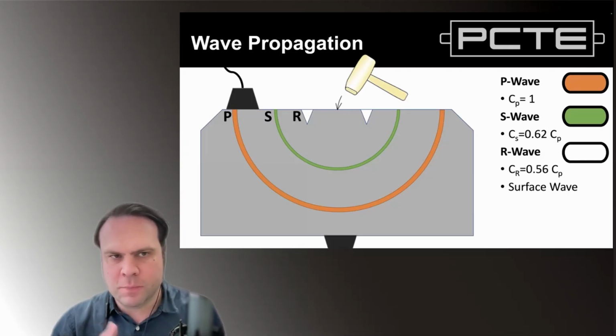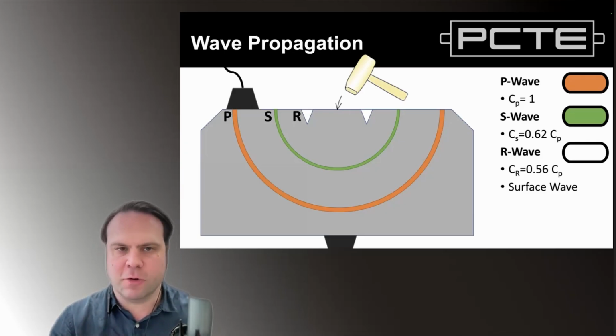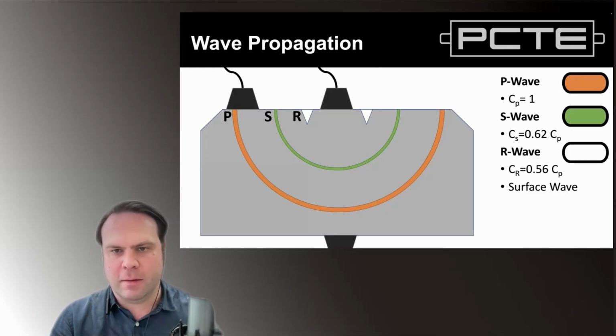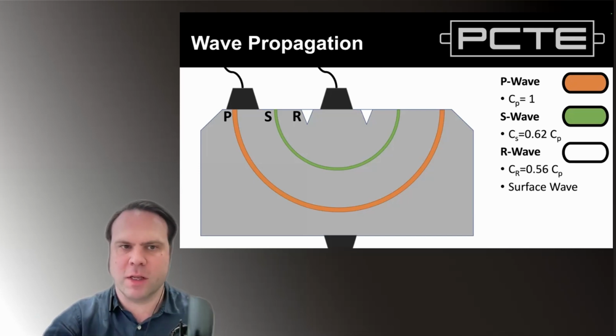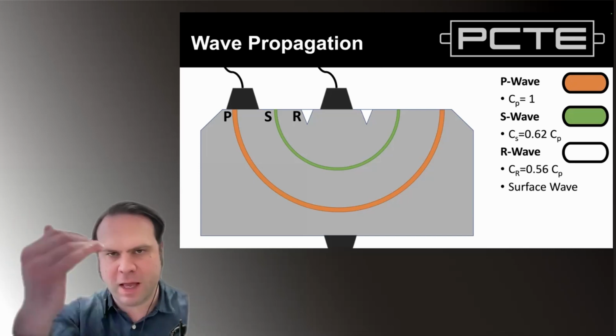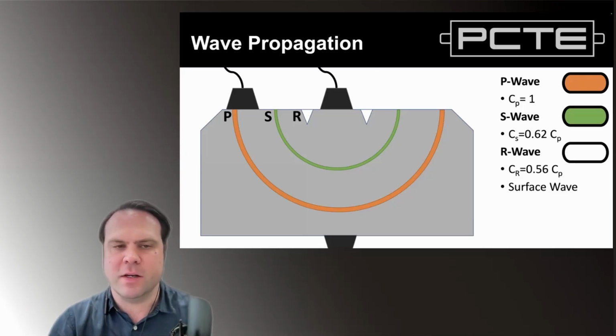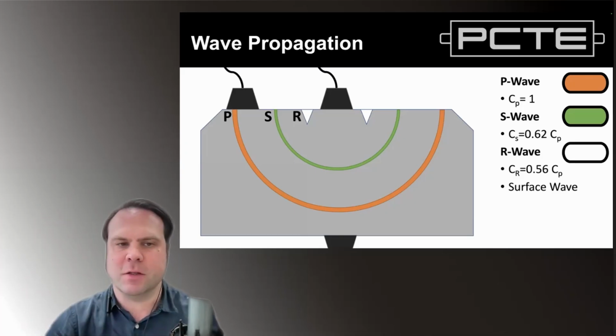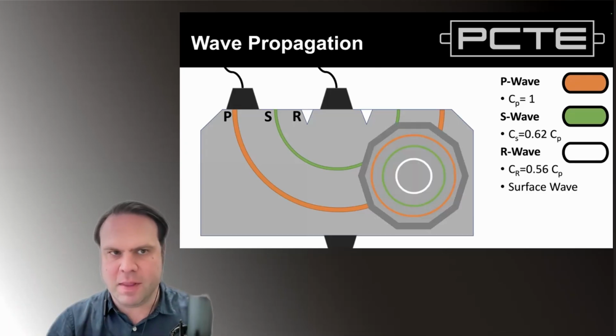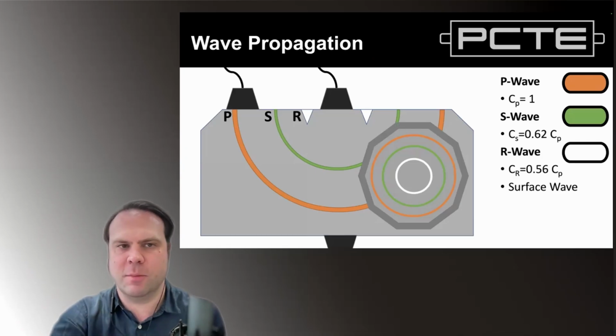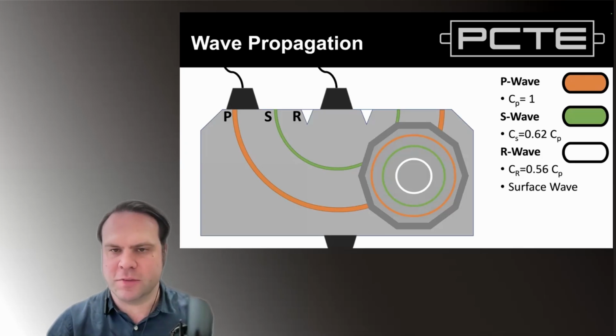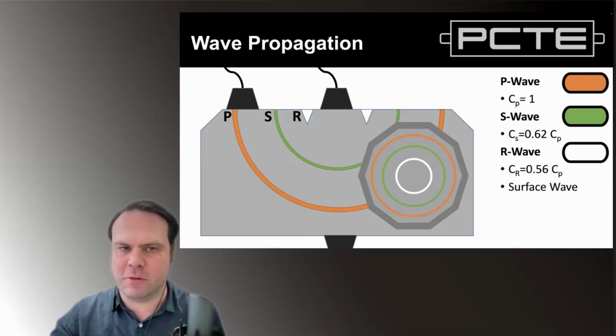So furthermore, there are other techniques we use during this testing. For example, the most common ultrasonic non-destructive test is ultrasonic pulse velocity. That's also usually done as a compression wave test, simply because if we have a sending and receiving transducer, the energy is going to go from the transmitter to the receiver the fastest in compression wave, and it's more difficult to isolate that compression wave energy. The other thing is, from our strike source, the energy is omnidirectional, so sources of interference can occur anywhere around the region of the strike.